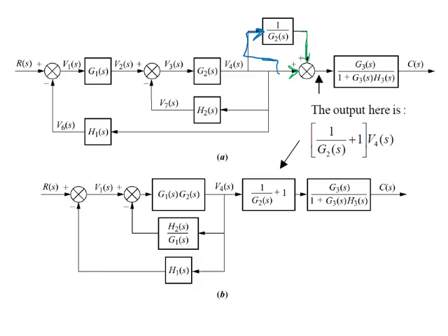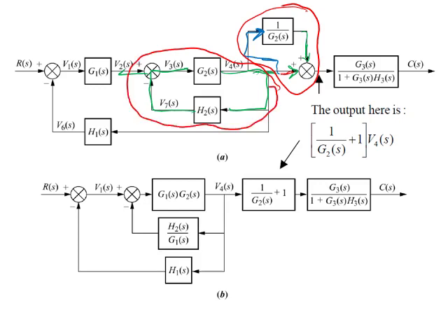And at the same time, look at this one here. It's feedback. So now I can say that this part is to be taken as parallel, which equals 1 over G plus 1. Here it's 1. Any empty signal is considered as a 1. With this one, this part is going to be feedback. So once you do them, the system will look easier.